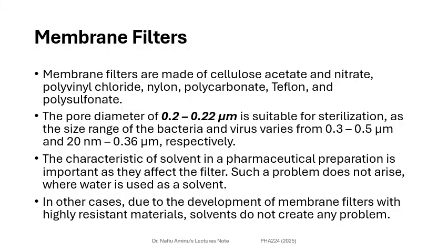Okay, so accordingly, based on that, certain bacteria can be identified, especially the bacteria, because when you look at this range here, it is mostly suitable for bacteria because viruses are much smaller. We have viruses that can actually be in the size of up to 0.02, which is below the size of the perforations of the filter media. So these filters are mostly suitable for bacteria because of their pore size. Okay, so for the viruses, we have other filters that can do that job.